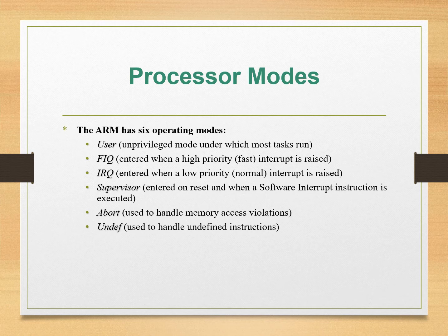Abort is used to handle memory access violations. When you have a fault, normally you will go into the abort mode. Then we have undefined, which is used for undefined instructions. A faulty instruction will also use the undefined mode.